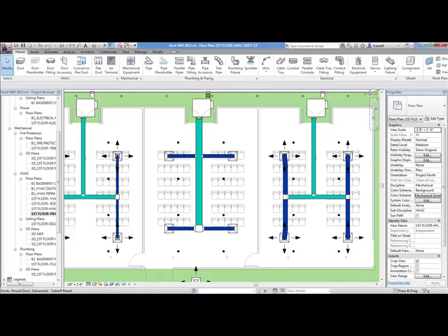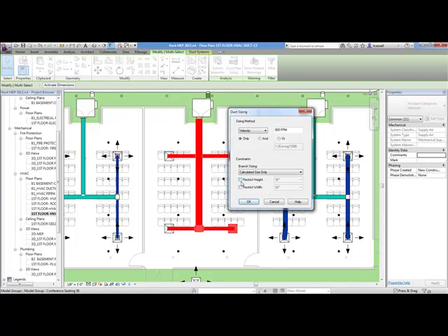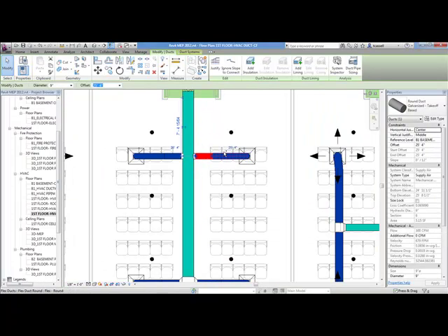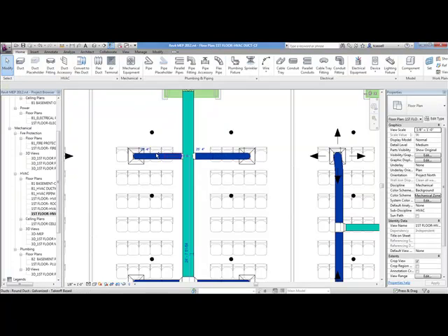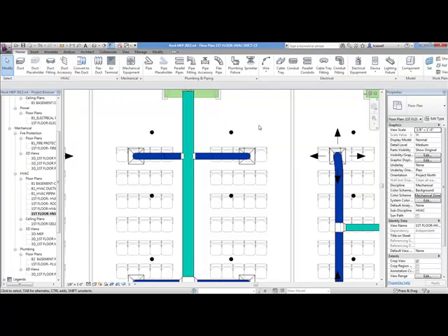Now when I do that and tell it to calculate, I get options for calculating, such as use even sizes only. I can even control what duct sizes are available, restrict height, larger of connector, so when it connects to a VAV unit or to a diffuser and air terminal, it'll match the size on that air terminal. That ever common 9-inch size duct that you don't usually use, I can now take that and adjust it and make it 10-inch duct. So you aren't restricted, but the duct pipe size calculator is going to help speed things up quite a bit.